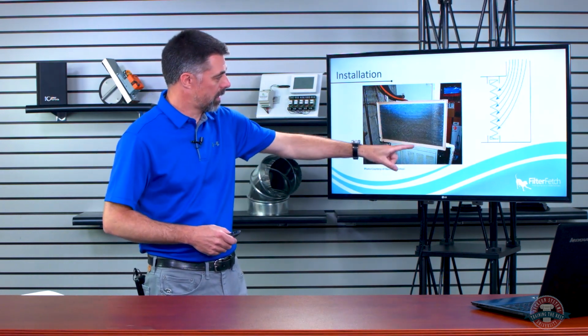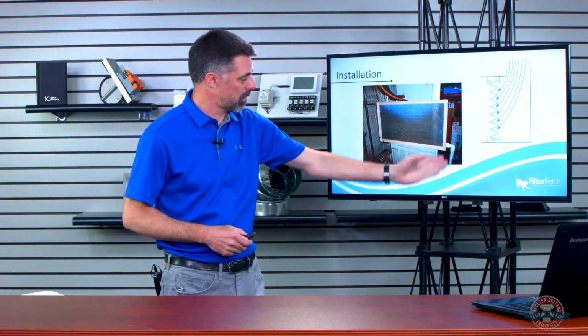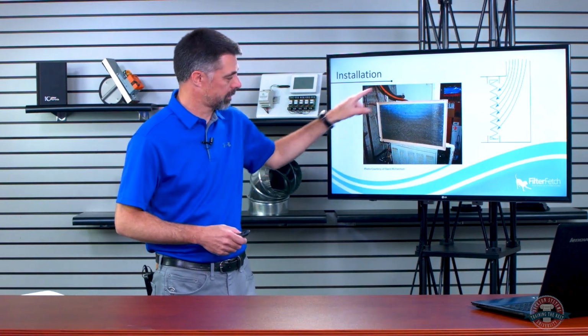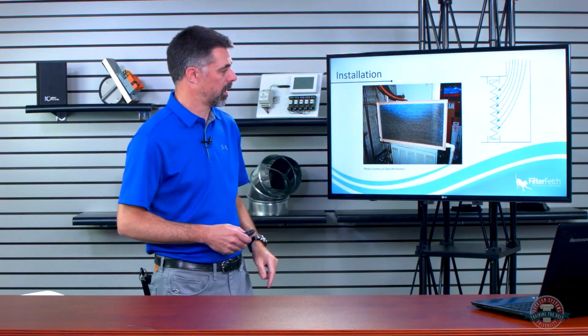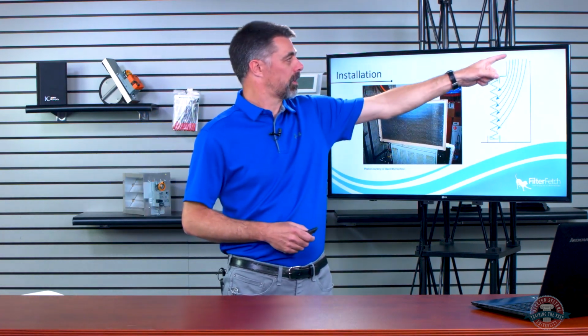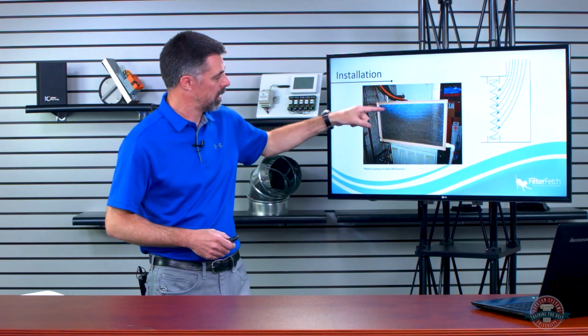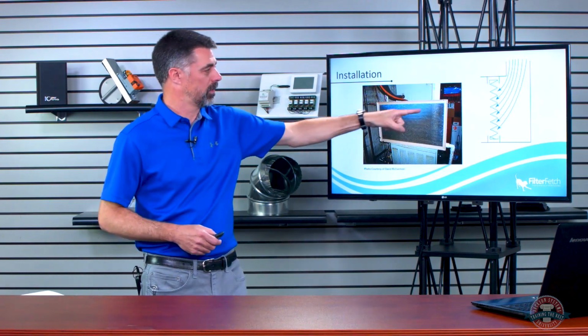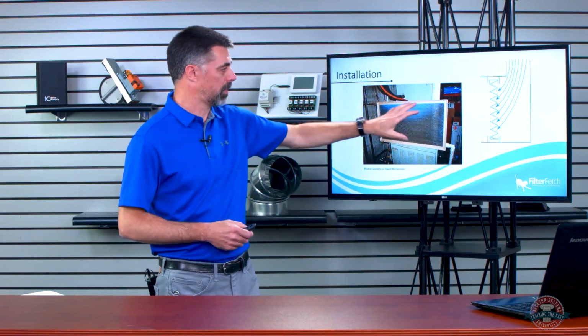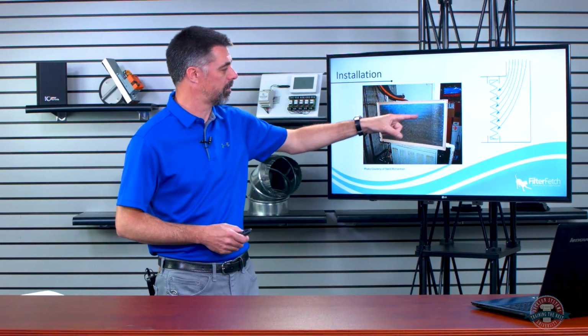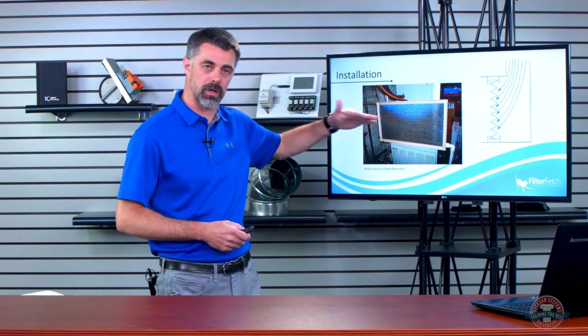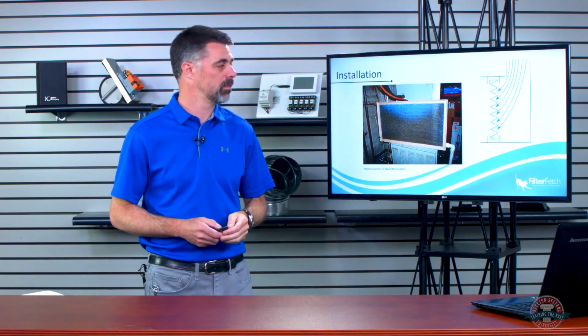This came out of the furnace it's sitting on here, and the return drop's over here, and it's got a perfectly sized filter rack in there. But the velocity was coming down here so fast, and that air would not turn that corner, right? So it wasn't even using the top part of this filter. It was wide open, not blocked at all, but it wasn't using the top part of that filter because that air would not turn and go straight into it.